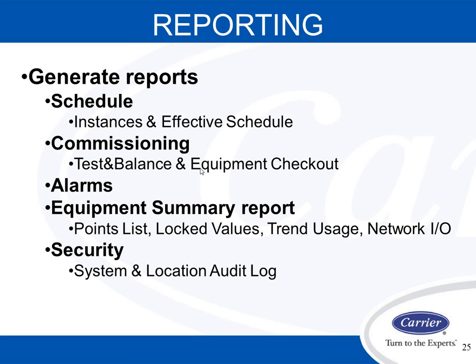It's kind of nice to go in there and just see the locked values points. If the system's been in use for a while, sometimes we tend to go in there and lock points to test things, to verify operation, and sometimes we accidentally leave them locked. So it's always nice to go in there and check out the locked values report and verify that nothing's locked and all operations doing well.